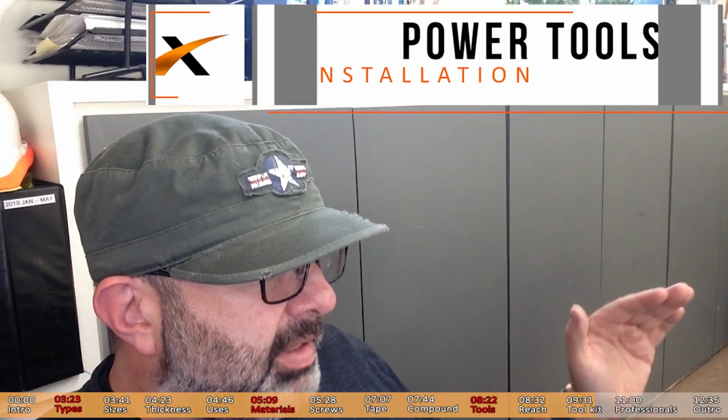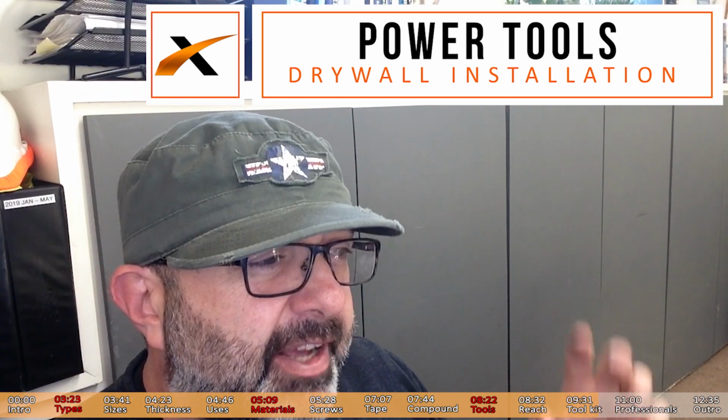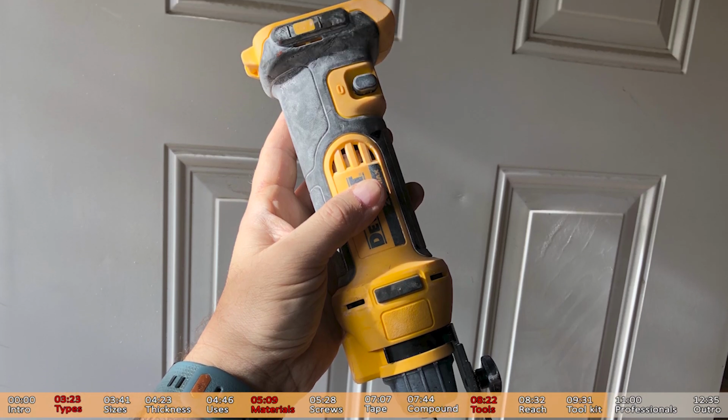Okay, under the same thought, there are 2 power tools that you may use to get your job done professionally, and it's gonna be very handy. Number 1, the cordless drill is ideal, but if you want to do a lot of drywall, a drywall specific screw gun is the way to go. Also, a plunge power cutter. Some of the people call it rotozip, but it is basically a puncher power cutter. It is a router with a drill bit that goes inside the drywall. You set it to the distance that you want so it doesn't hit any of the studs, and you can cut it in any shape you want.